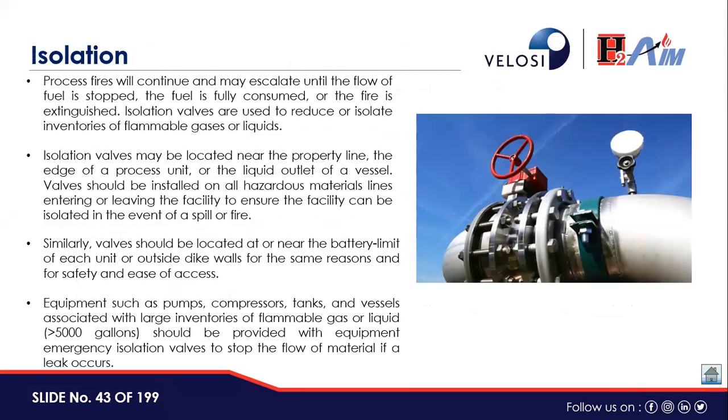Now, isolation means what? Isolation means if there is an event in a plant and there is hydrocarbon coming to the plant from another facility, then due to the ESD system or due to a manual system or ESD valves, the incoming fluid should be stopped. That is called isolation, or stopping the incoming fluids.